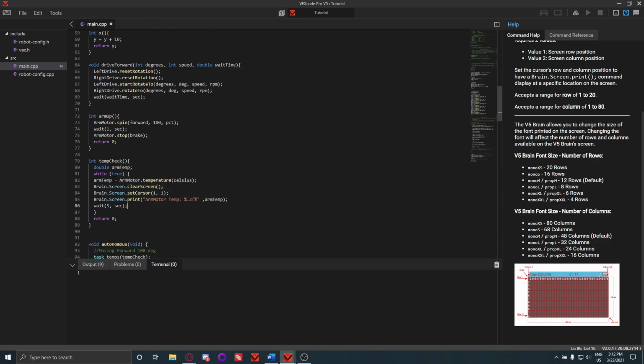So I would definitely recommend mocking up something like this for all of your motors, because a big thing that can cause deviation between autonomous runs or driver runs is when your motors get too hot because you've been running them for a while, and then they have to thermal throttle.